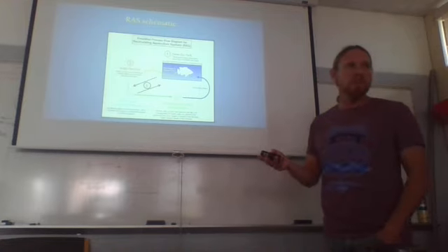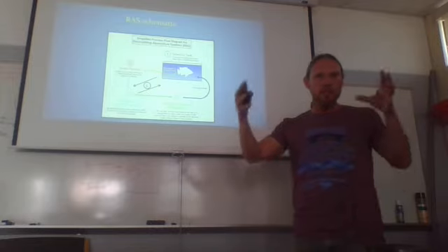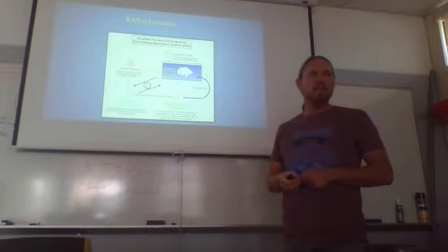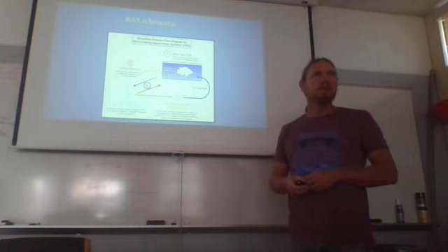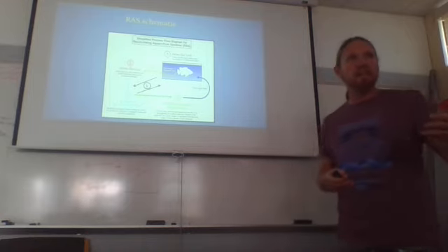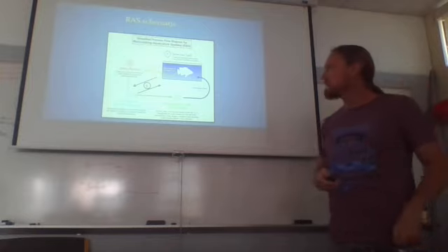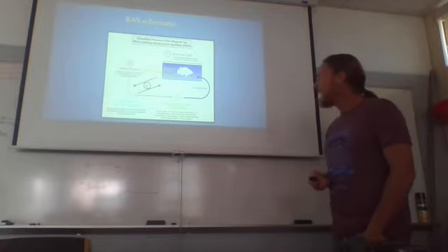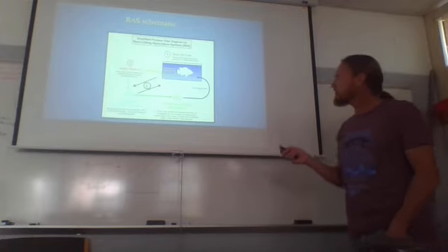There's other kinds of sterilization too. You can use ozone gas bubbled into a chamber that is pretty effective at killing most microbes in the water. Some danger there. If that ozone doesn't get degassed before it gets back into the tank, you can poison your animals with it. Here's just a simple flow design.